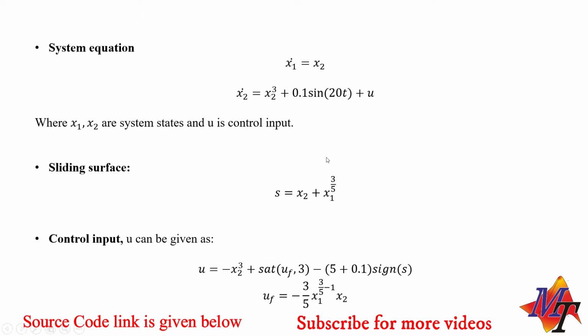Now for designing the sliding surface, we have taken x2 plus x1 raised to 3 by 5, and for calculating the control input, we have taken minus 5 sin s as the u d part, whereas we have differentiated this, s dot equals 0, and we have calculated the u equivalent part, which is minus x2 cube and minus 0.1 sin s, and saturation is used because of the singularity problem present in terminal sliding mode control approach.